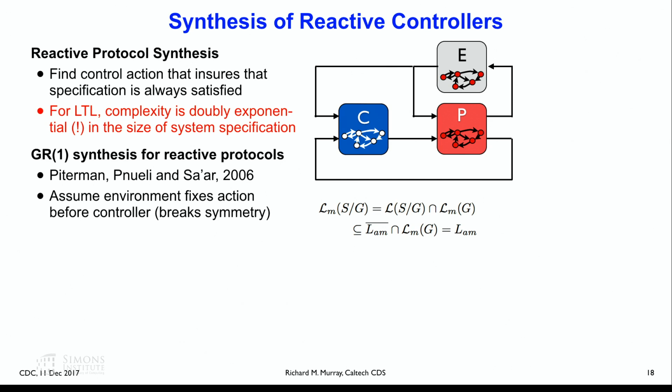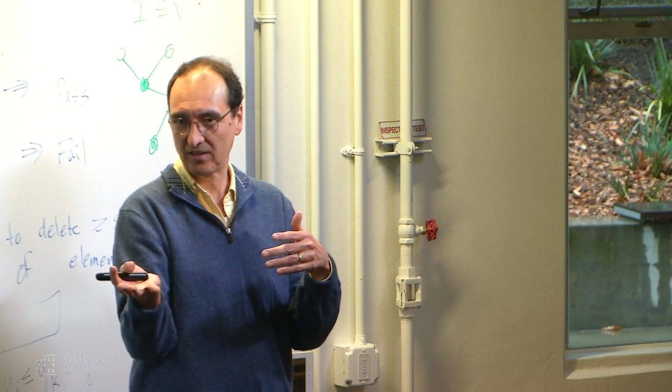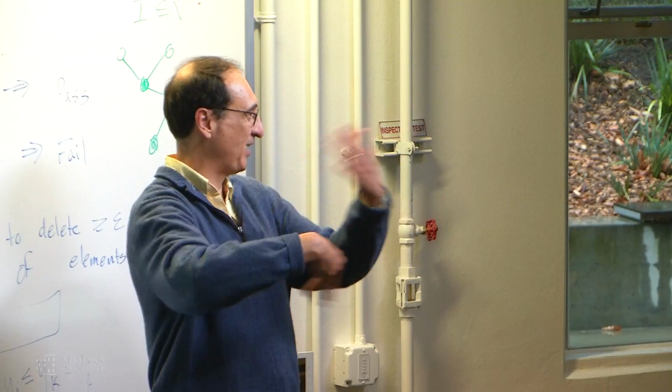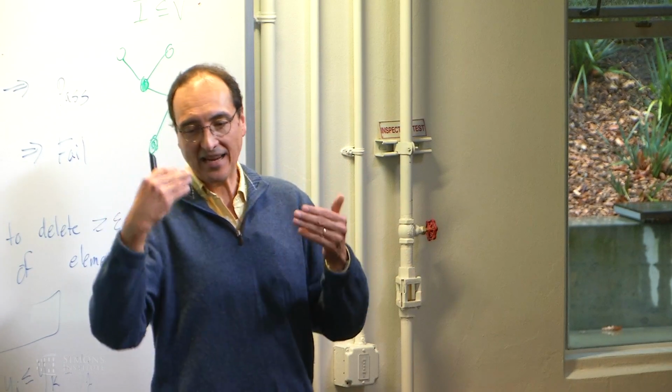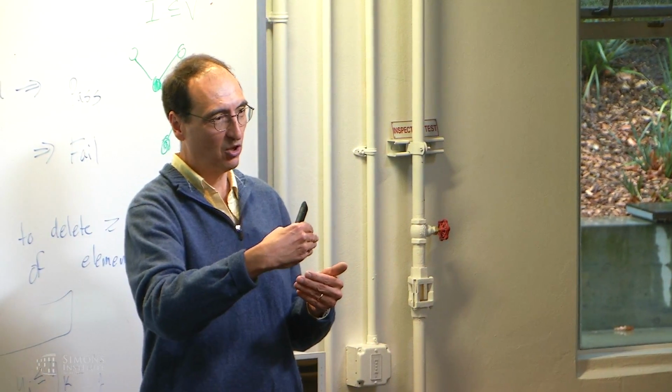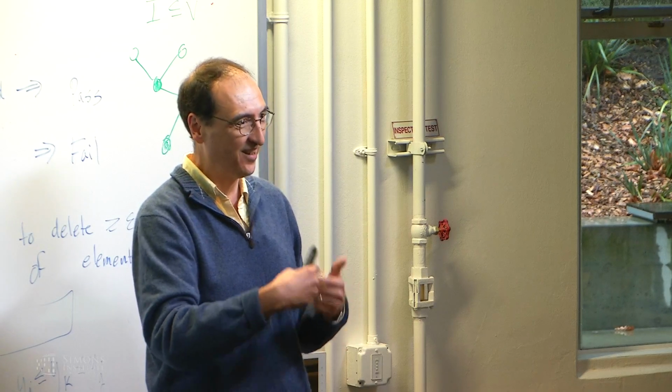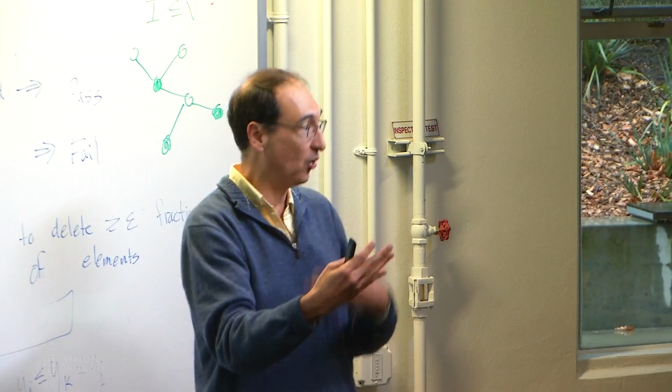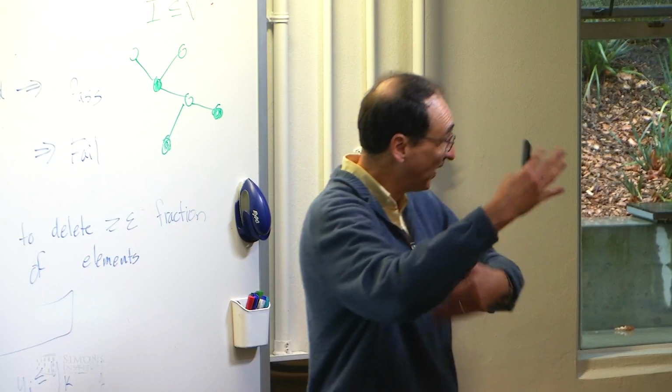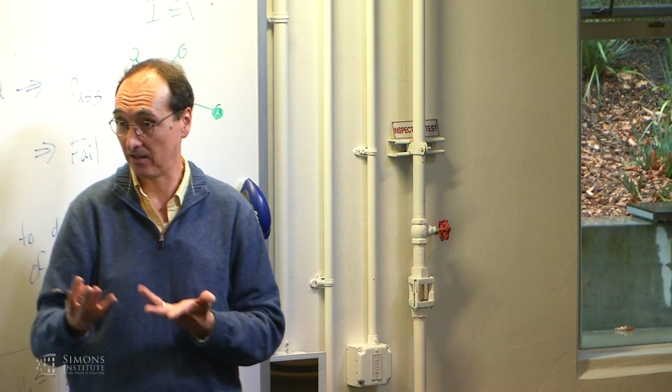And that's not too bad, because you can say, well, that's not fair. Why should you get to see what the environment's going to do? But I'm running in this iteration. So I can say, I see that the person's starting to turn. As long as for the next 100th of a second I assume they're starting to turn, if they stop turning, I'll know 100th of a second later and I'll replan. So if you go into this receding horizon framework, you can deal with this.